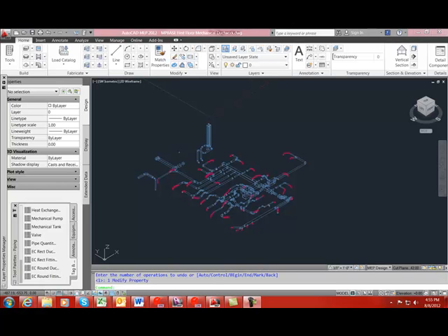Once you import a selection from Revit MEP with MEP Design to Fabrication, you will want to assign the correct system to all of the ductwork in Fabrication for AutoCAD MEP. Assigning the correct system will make the ductwork much easier to work with. If you have exported the selections by system from Revit MEP, then this step is very straightforward.